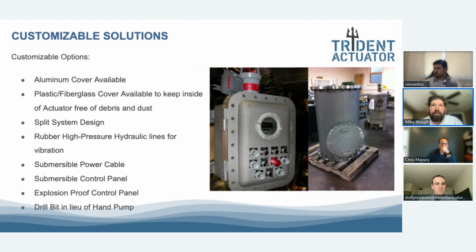But once again, with that high pressure hydraulic oil, if something were to occur, we prefer that it be enclosed in something. We have some custom designs like split systems based on fitment needs in the areas. Our standard is stainless steel hydraulic tubing, but we can use the high pressure rubber hose that you see if there's vibration issues.